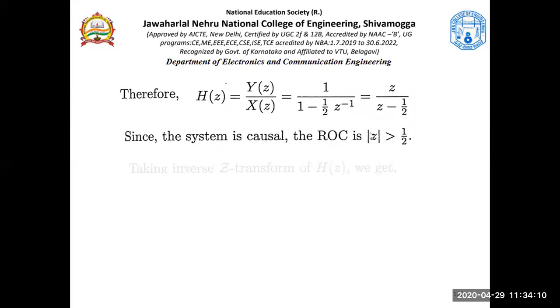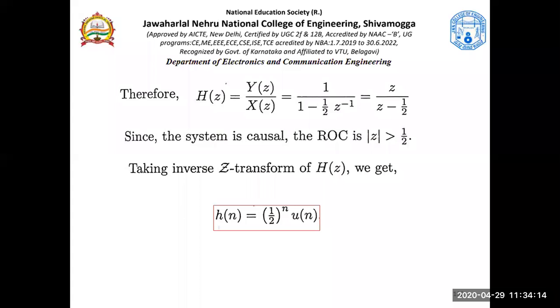Now what would the inverse z transform give us? The inverse z transform of H of z is h of n. And what is the inverse z transform of this? The positive time sequence, it is (1/2)^n u of n, and this is your impulse response. We had the transfer function here. The inverse z transform of the transfer function gives us the impulse response, which is this. Everybody understand? Okay, let's quickly take another problem and let's end there.